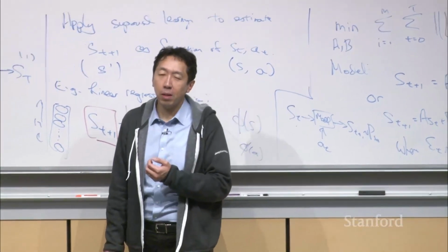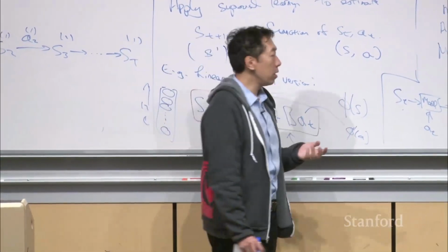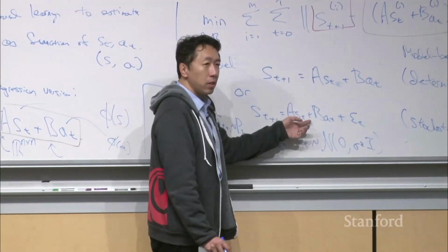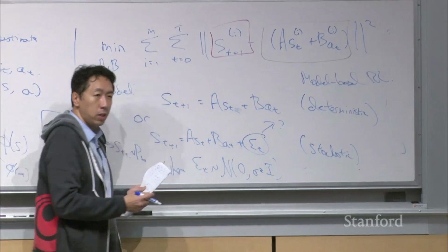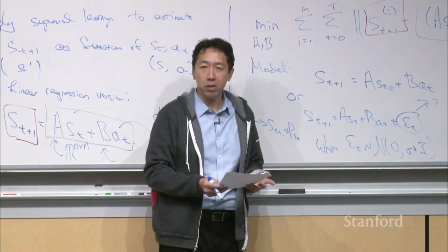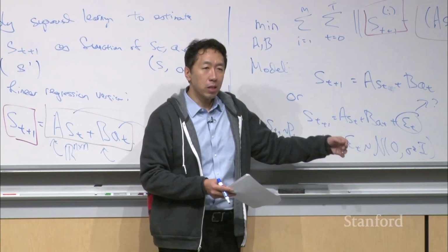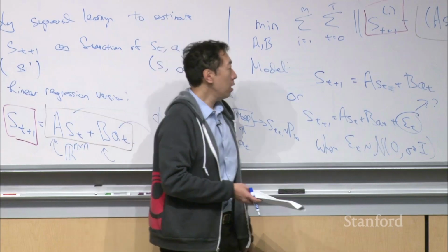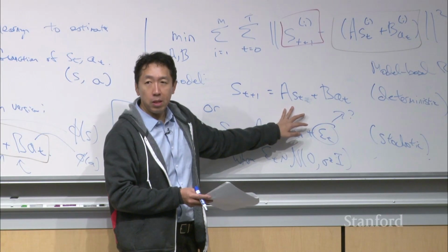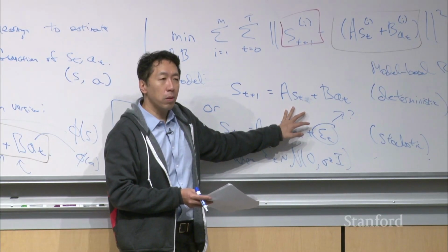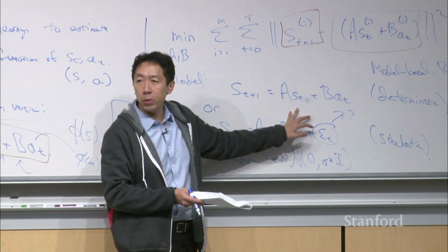And just one last tip. One of the things we learned building these reinforcement learning algorithms for a lot of robots is that, having run this model, you might ask, well, how do I choose the distribution for this noise? How do you model the distribution for the noise? One thing you could do is estimate it from data, but as a practical matter, it turns out if you use a deterministic simulator, a lot of reinforcement learning algorithms will learn a very brittle model that works in your simulator but doesn't actually work when you put it into your real robot, right?